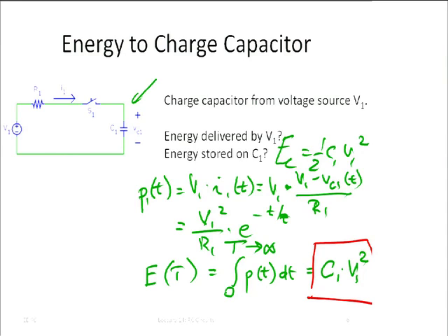In fact, when I change the value of resistor R1, there is one thing that changes. What does change? Exactly, right? If I have a very large resistor, it takes forever to charge this thing. For a very small resistor, it takes very little time, and anything in between, right? And so I may, in practice, choose the right value of resistor so that the battery doesn't get too hot during the charging process or whatnot.